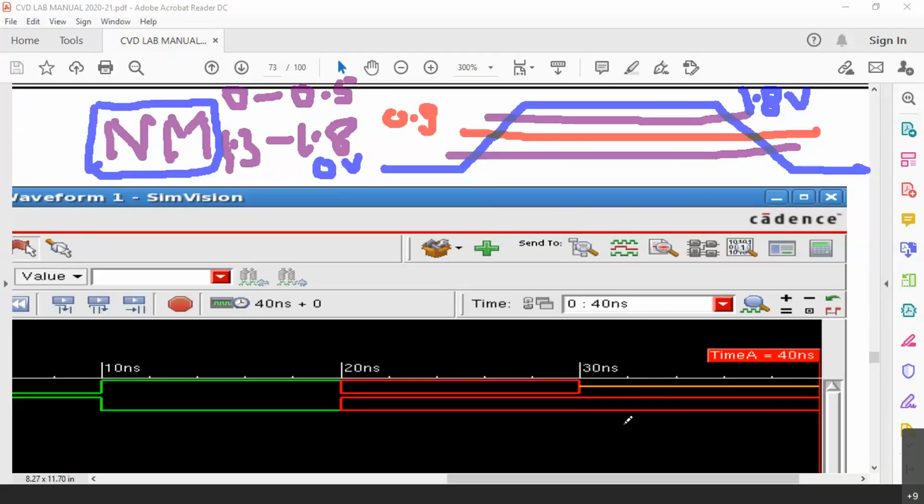Right now, inside the tool, they are all standard cells. They are not full custom designs. In analog, it is full custom design, where we design the MOSFETs and the inverter using the layers. Whereas in digital, they are all standard cells, and using standard cells we are going to simulate. Even a MOSFET is a standard cell here, characterized for the given technology. So the tool will not bother about whether the output has to be Z. Output can be X. Output need not be VDD by 2. Output can be above or below, depending upon the transient behavior of the switches.